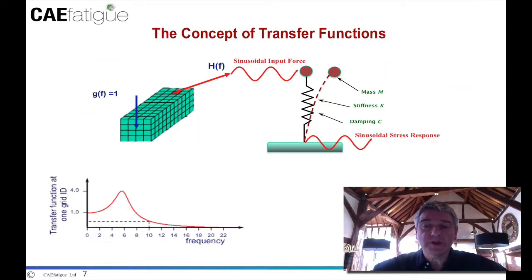One of the reasons why the frequency domain is such a powerful analysis environment is because it allows us to define structural behavior using what we can call system transfer functions. And unlike working in the time domain, these system transfer functions are properties of the structure and not the loading. The process of identifying these system transfer functions can be reduced to the relationship between sine waves of load applied to the structure and the resultant sine waves of response.